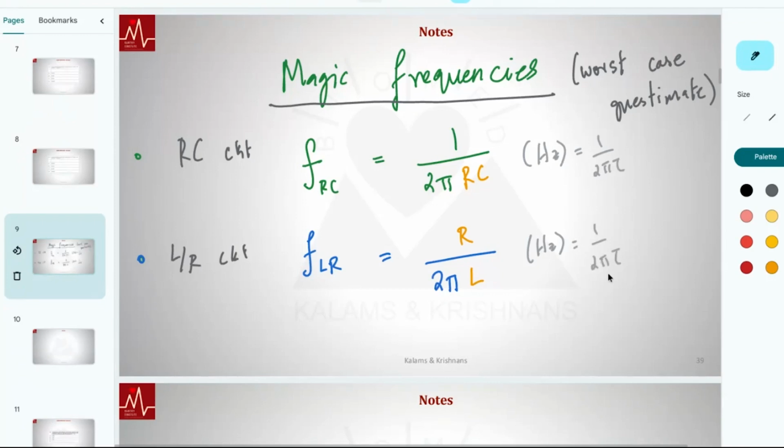There is a relation between parameters in the transient circuit and parameters in the DC circuit and AC circuit. In the transient circuit, it is a time constant. In the AC circuit, it's going to be the frequencies. Janil asked a question, right? Notice, omega is 2 pi F. That happens to be 1 by RC. Notice 2 pi F happens to be 1 by RC, and 2 pi F is omega. That tells you omega is 1 by tau.